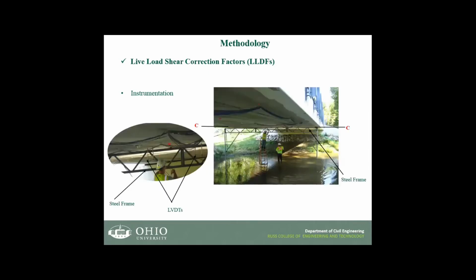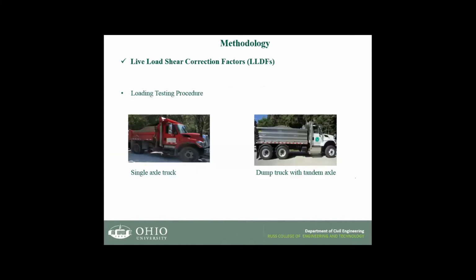This is showing the frame that we built the day before the testing to support the LVDTs. If you see the picture, there is a frame, and in the small picture, it shows where the LVDT is. And on the day of the testing, we used 2 trucks, a single axle truck and a dump truck. The weight of both of these trucks was taken on the day of the testing.